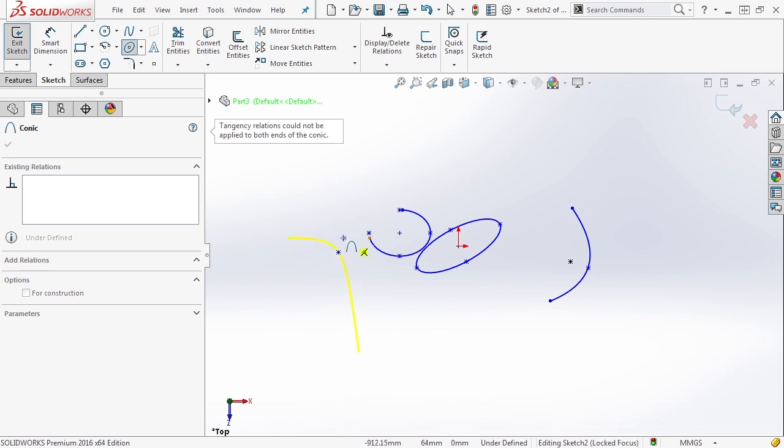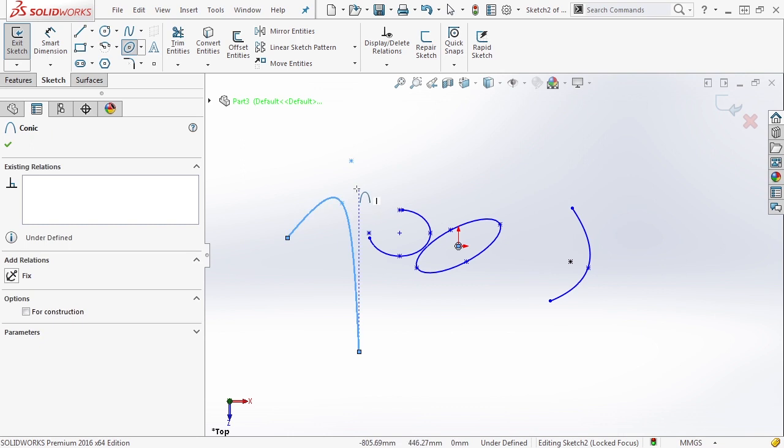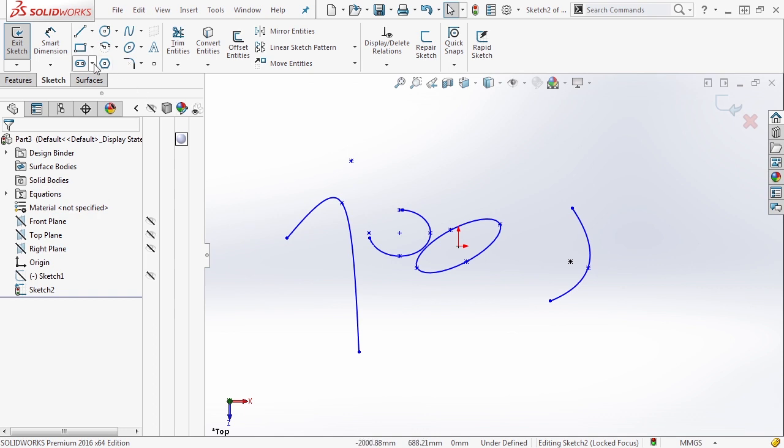Once we select the endpoint of this line, you'll notice that we start by creating a curve. Now, this curve is essentially a slice of a cone in 3D. Once we select that point, then we need to determine the rho value. Now, the higher the rho value, the sharper the transition in the corner. The lower the rho value, the more gradual the transition is. Of course, you can define these as well by adding dimensions, but right now we're really just focusing on what geometry gets created.